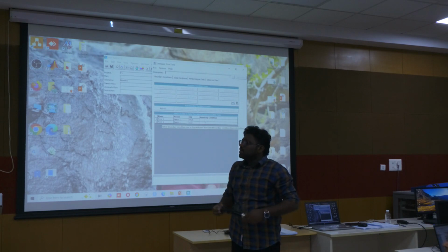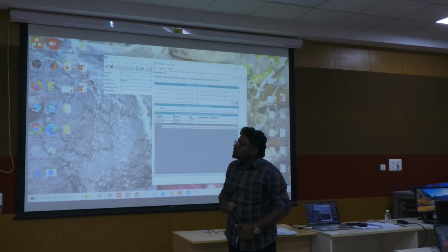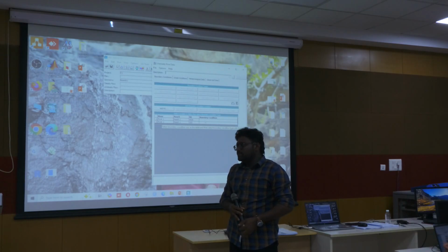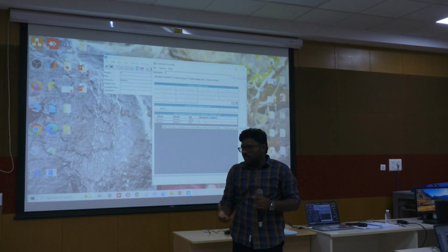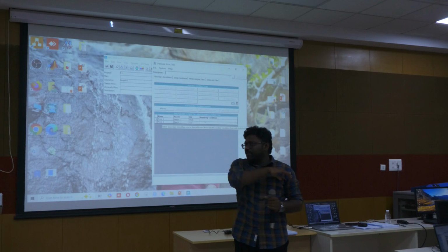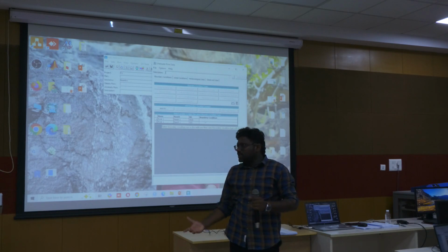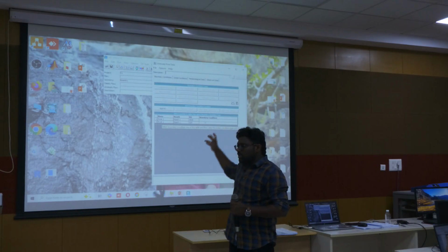In real time, we have two basic systems, one at the upstream and one at the downstream, where we fix the upstream and downstream conditions. If we have real-time data, like Q in upstream and downstream, that can be fixed and given here. What we don't have is the downstream water level data, which is why we are going with the indirect way. If you have water surface level data or stream flow data downstream, you can directly give that. There are multiple options, I will show you.